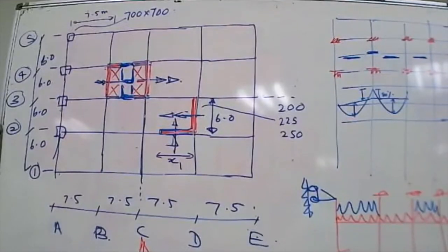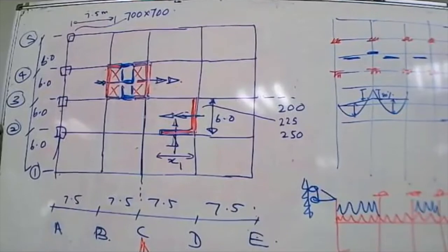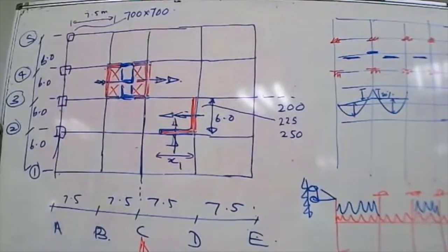So you select the size of the beam, and last time I explained how to select the size of the beam. I said under different situations, even for higher spans, we use say 600 millimeter overall depth, and then if you have any problem in the other direction, you can select a suitable beam size. So basically, the whole idea is to ensure the column is bigger than the beam, not vice versa.